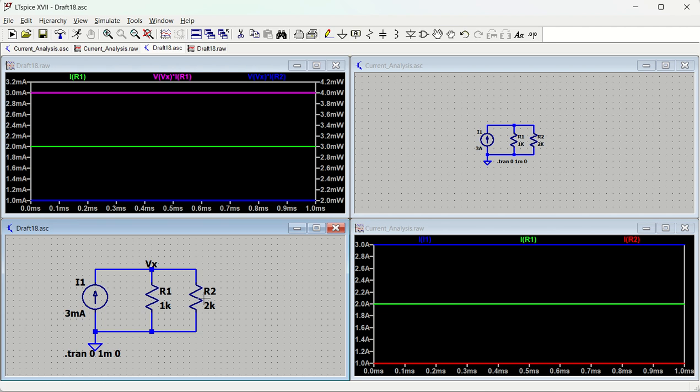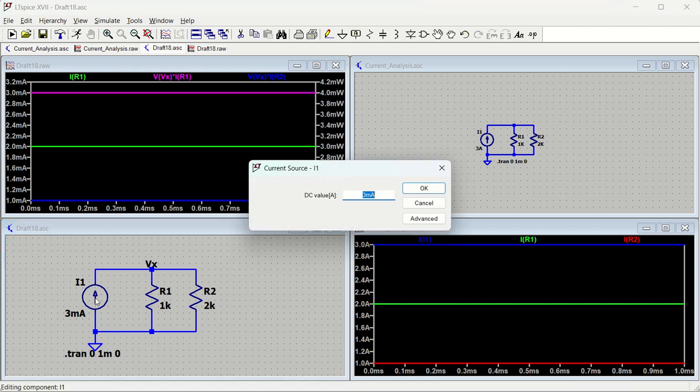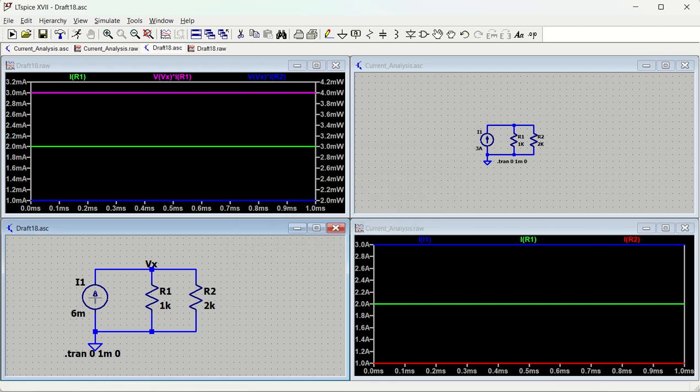because the current is actually less, like 1 milliampere only. So 1 milliampere multiplied by 2 volt, that is 2 milliwatts. Understood? So good. If you want, you can change the value of current. Let's say 6 milliampere I want, or 6 mA if you put, that will also be 6 milliampere, not a problem. And rerun that, then all these values will change, right?